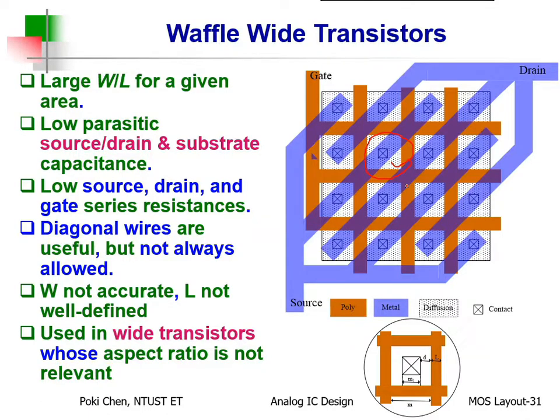Especially why we need such kind of very huge W over L. For what? Very high driving capability. So the first application flashed into my mind is power electronics. For power electronics, you need to have power PMOS, power MOS. Wow. How much for this? To my memory, for usual application, maybe at this order. Wow. 10,000 microns. Don't do the layout for a single finger.